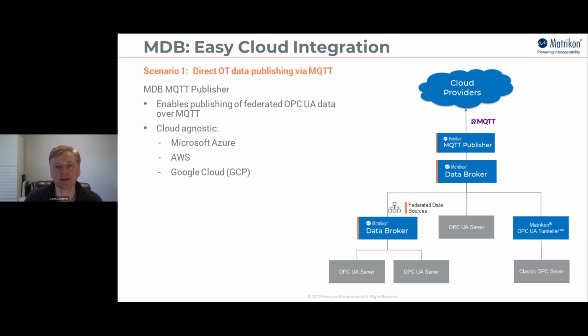Now there's a number of things there, and it's a whole other conversation, as some people are confused and say, well, it's MQTT versus OPC UA. It doesn't have to be that way. MQTT is a transport. OPC UA can use the transport. So whether you're doing pure MQTT, which is just sending values over that transport, or you're doing OPC UA over MQTT, the point is MQTT is well designed, well suited for edge to cloud communications. It's publishing it out. It works great in that direction.